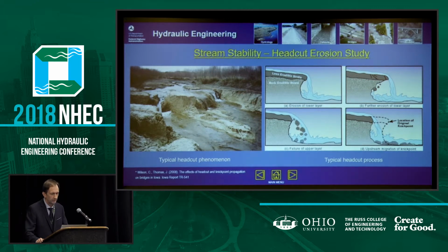You have a lesser erodible strata and below it a more erodible layer. As the flow plunges, like a weir flow, over that lesser erodible strata, the more erodible part gets undermined and creates a head cut, and the channel and that cut move upstream.